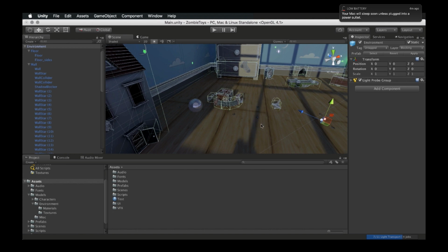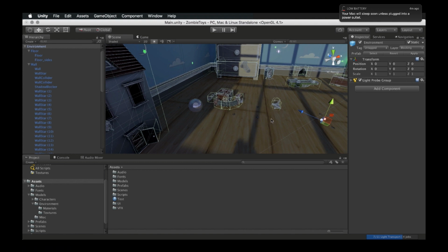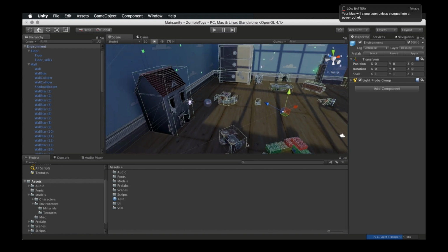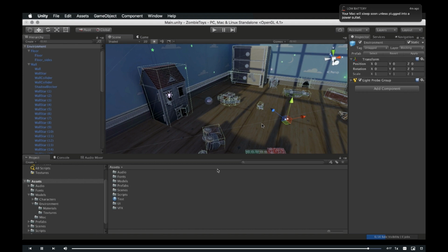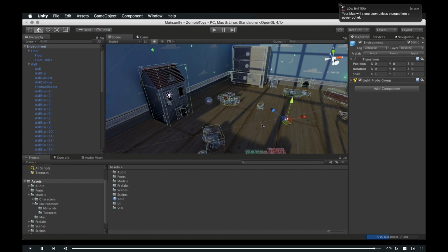For now, though, I'll add reflection probes only on those objects that might see something, or reflect it, very close and are already fairly shiny. I'll put a reflection probe onto the train, the blocks, the fire truck and the robot, and also the clock, as it has a glass face. I'll leave the reflection off the walls, dollhouse, and drawers, as those are matte objects. As an artistic choice, I'm going to leave the reflection probes off the floor for the moment. We can always add them in later, but this may be too big for one probe, and we may get some odd reflections or too much of a computation load.